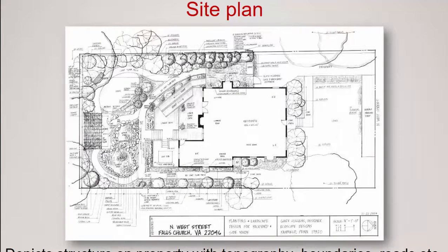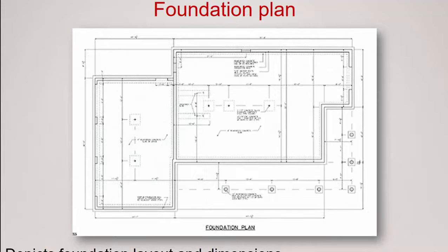In this site plan, we can see even additional detail. Predominantly, what jumps out at you is the landscaping, the plantings that surround the building. You can see the trees, the bushes, the lawn, and such. The next plan typically seen in a set of construction drawings is the foundation plan. The foundation plan is the component of the building that supports all structure above. It typically details concrete or some other masonry product to really hold up the remaining part of the structure.